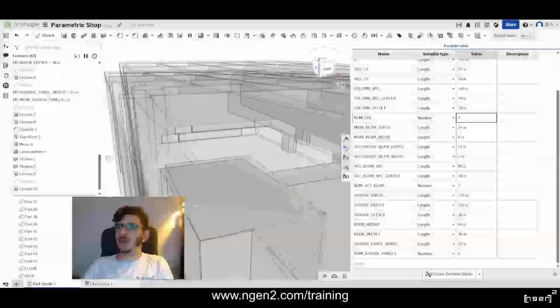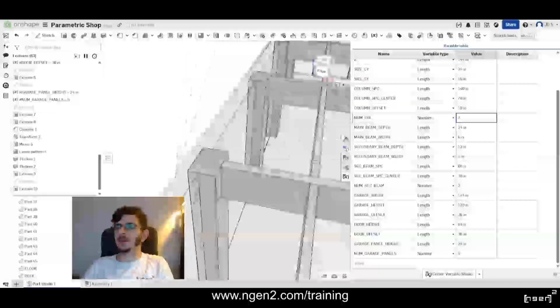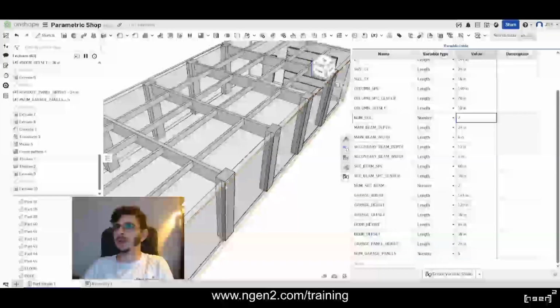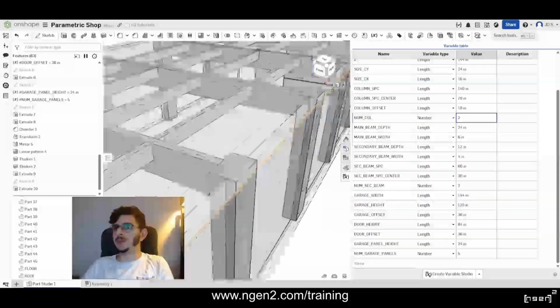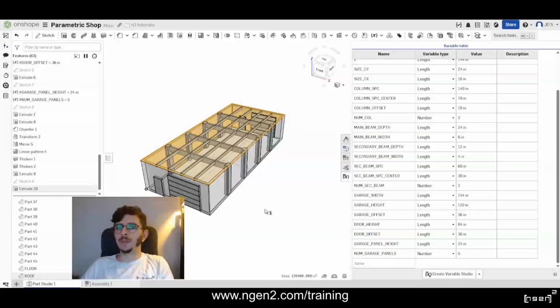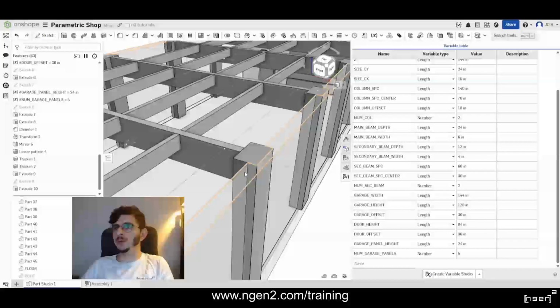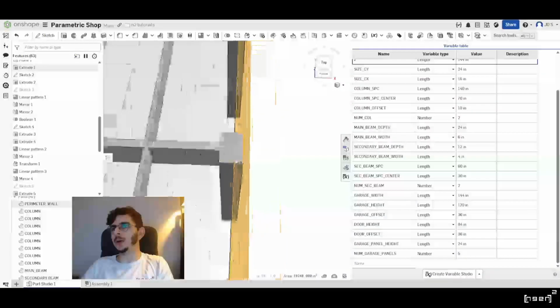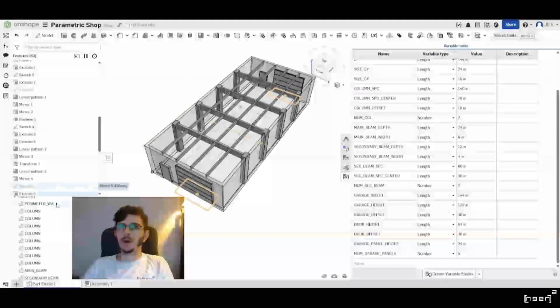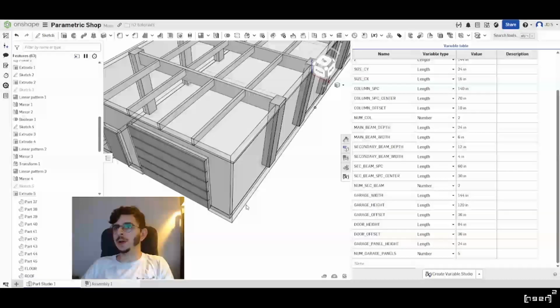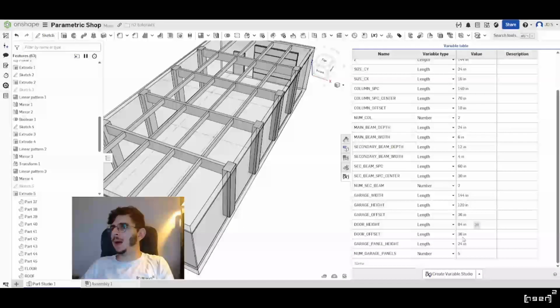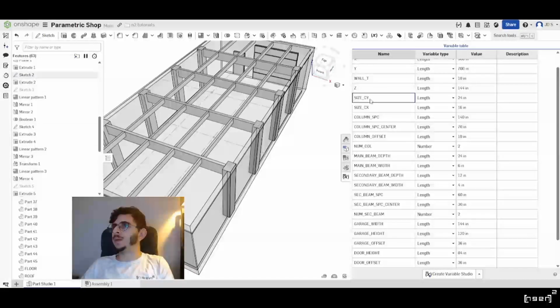So now we kind of have a notch with the wall instead of it sticking out of the wall. So you can see, if we hide the roof, this is like a notched part now, which for our modeling purposes is fine, but to combat that, we'd have to go with the column size modification in the X direction.